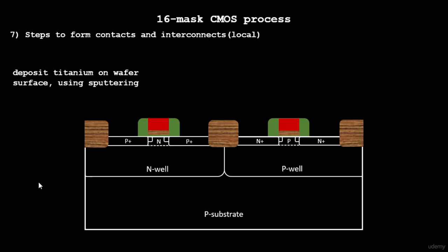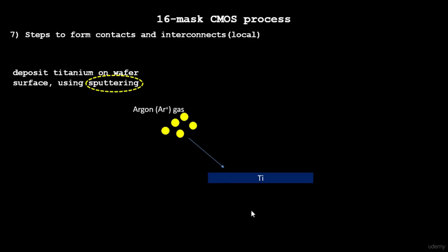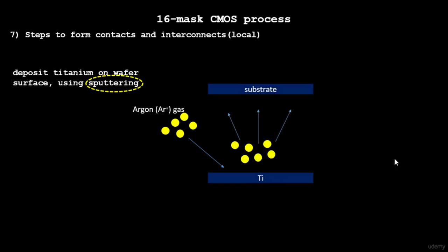So we are not done with this one, because we have to somehow maintain the further source and drain. When we try to generate the actual source and drain, it might get entered into this one, or this structure might just get disrupted. So we have to protect this lightly doped drain structure. How do we do that? We create some spacers over here. We try to create some sidewall spacers, and this is how we do it.